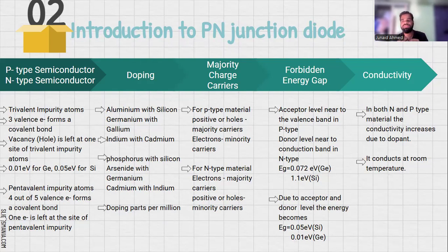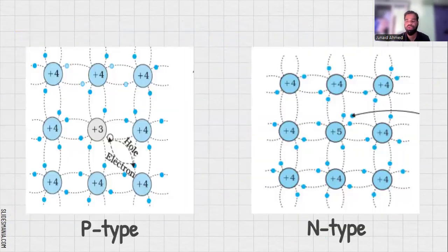So, what are the elements for semiconductor devices? The simple thing you can remember is that elements having four electrons in the outermost orbit are considered semiconductors. Here I am having silicon material. In silicon, in the outermost orbit we have four electrons, and if you want to make an n-type semiconductor, that is a negative type semiconductor, negative means electron, more number of electrons in that type of semiconductor.